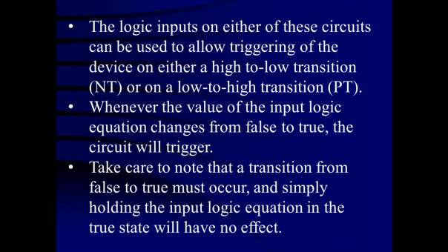Take care to note that the transition from false to true must occur, and simply holding the input logic equation in the true state will have no effect.